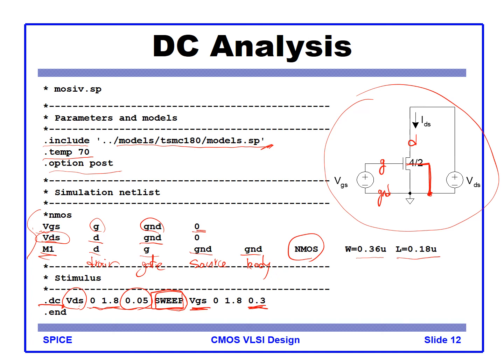But most students start with just transient simulation, and transient simulation doesn't give us any information on the device operating point. So when you run an analog circuit, you must run DC analysis first. Let's take a look at the output from this Spice deck.